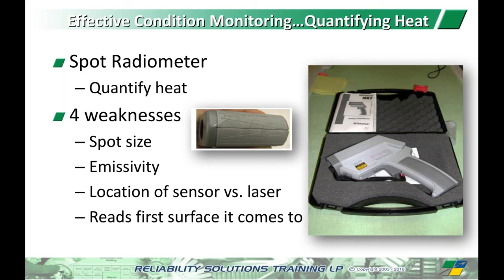In fluid power systems, we talked about flow makes it go, and pressure is force. The third principle that we have to consider is heat. Follow the heat. Whenever you're troubleshooting fluid power, we follow the heat. That'll tell you where the problem is.